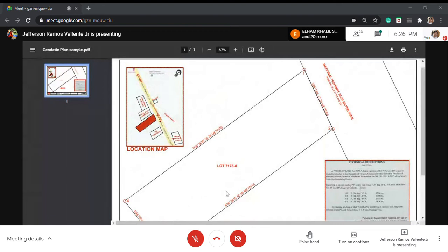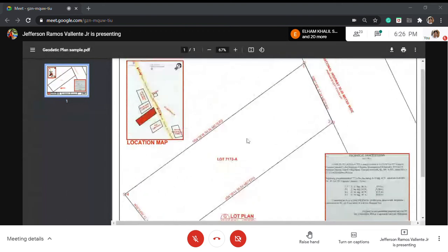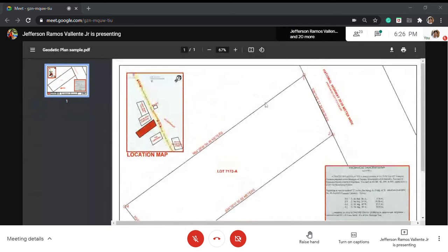So normally we position our first point relative to the north, right? Study view of our surveying, no? In point 1, it should go to point 2. So that's why here it's south 26 degrees. So if I draw a vertical line here, south 26 degrees goes from 1 to 2. So that's the angle created here.